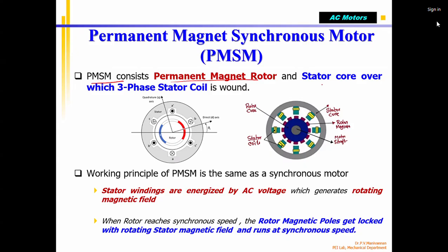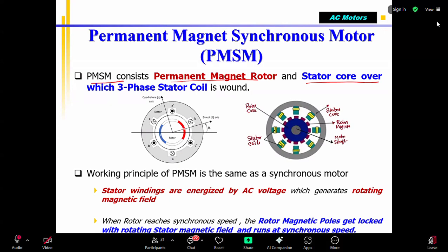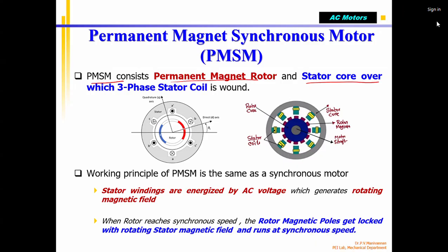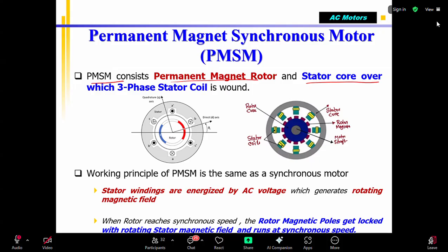Of course, it has a stator. Please note that any motor needs two magnetic fields which interact with each other, attract or repulse. So torque is produced, and if the torque is able to move the rotor. The stator is fixed, it is bolted. The body of the motor is bolted with nut and bolt on your bed.